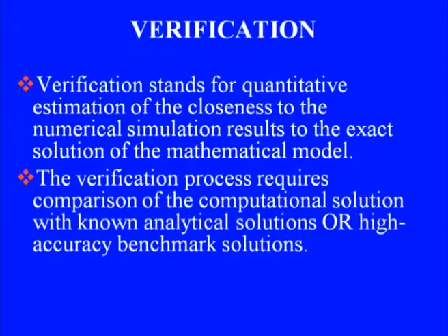Now, this particular process would ideally require that we should be able to compare the computational solution or CFD solution with known analytical solution. In fact, that is not going to happen most of the time, specifically if you are trying to solve Navier-Stokes simulations in complex geometries. Exact analytical solutions are simply ruled out. So, in that situation, our only recourse is what we call high accuracy benchmark solutions, which have been obtained using specified numerical simulation processes with very, very fine grids.